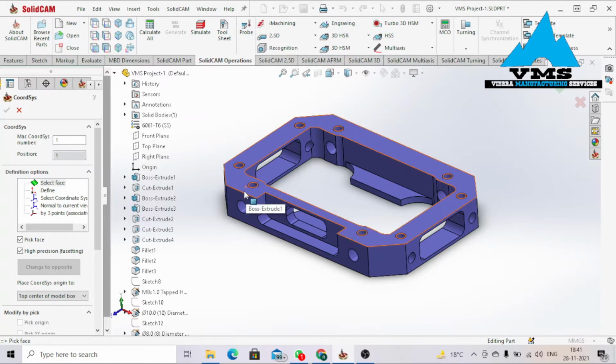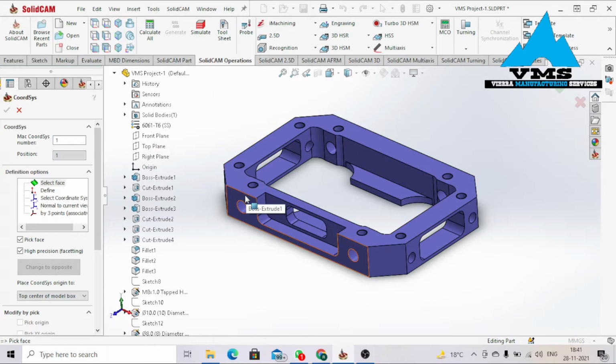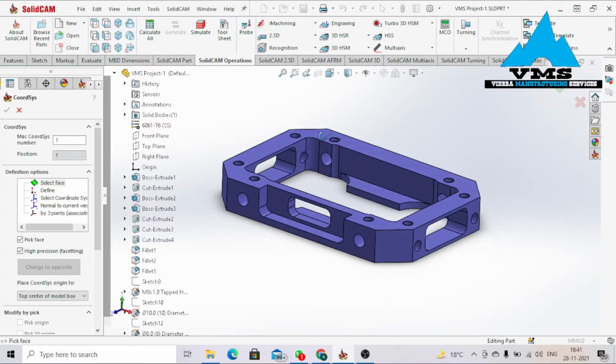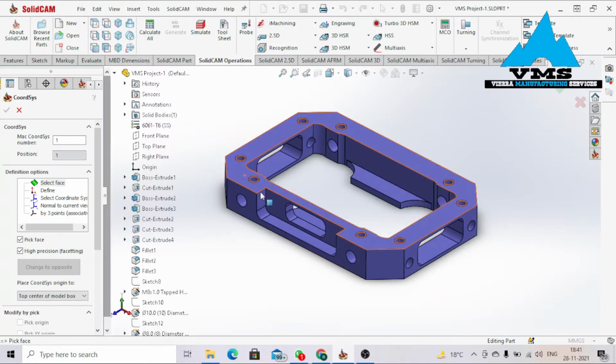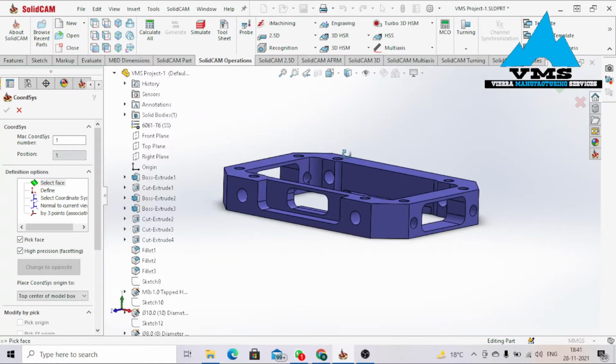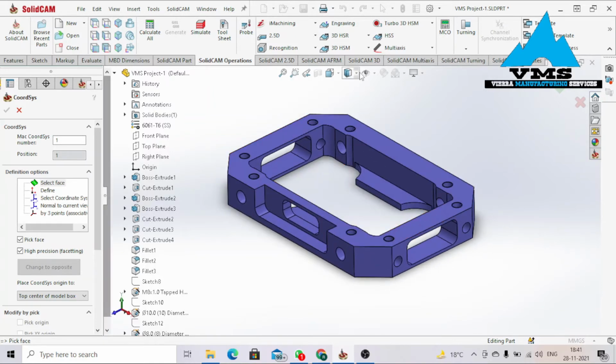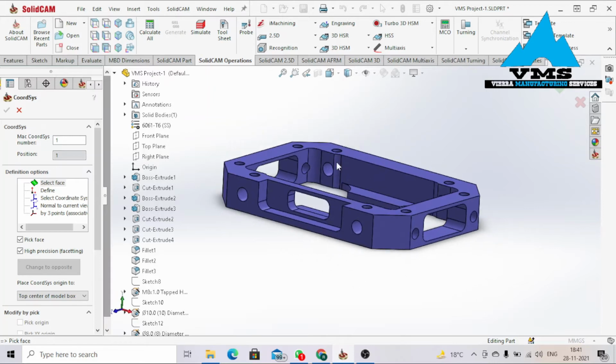And by the way, we can select many different types of offset. It's not just about putting one offset. We can put other offsets, maybe up to 8 offsets. Okay, so to put an offset, we are going to tell the machine that this is the part and the cutting tool has to begin from here, because remember that in a 3-axis milling machine, the cutting tool moves from upward to downward, that is in the Z direction.